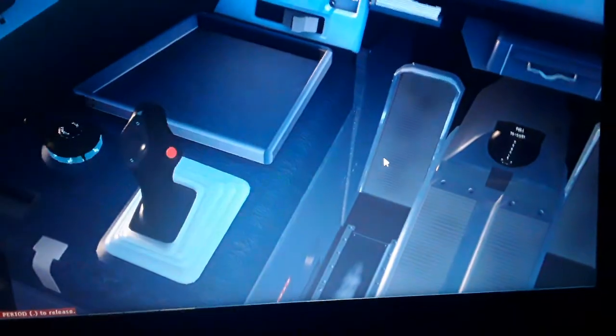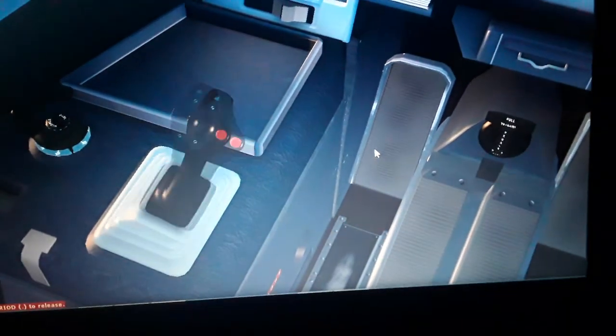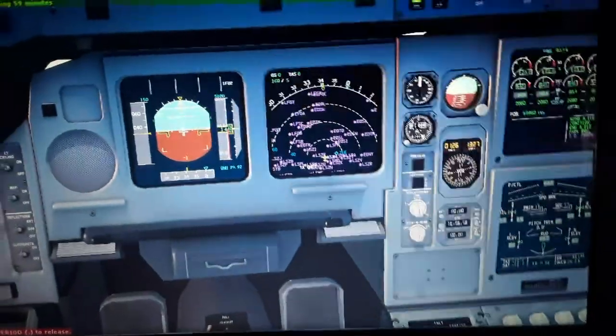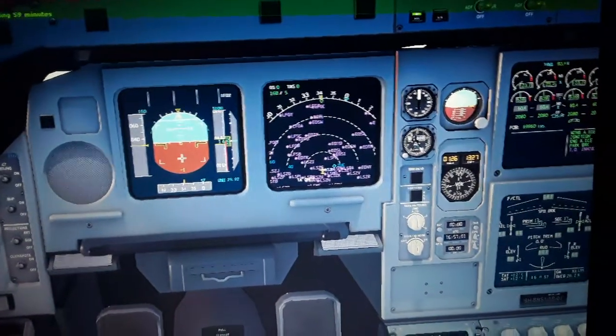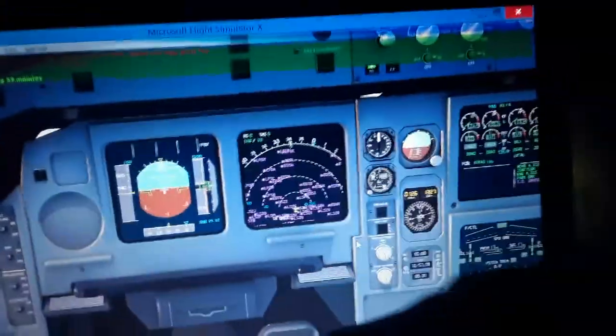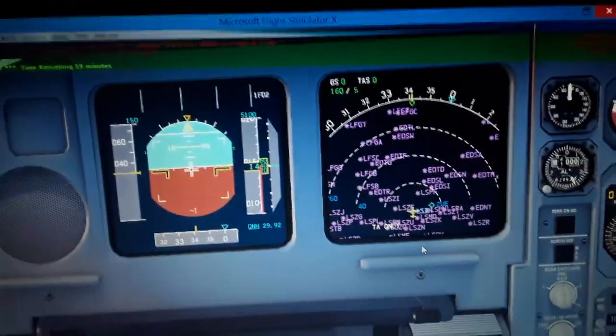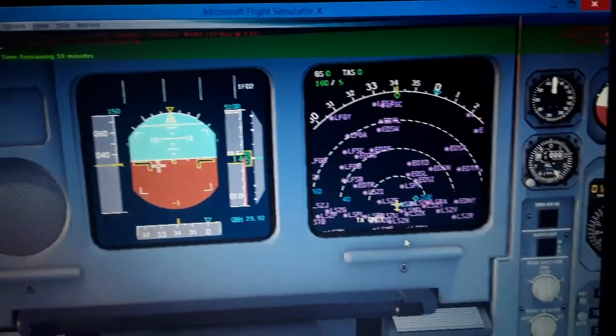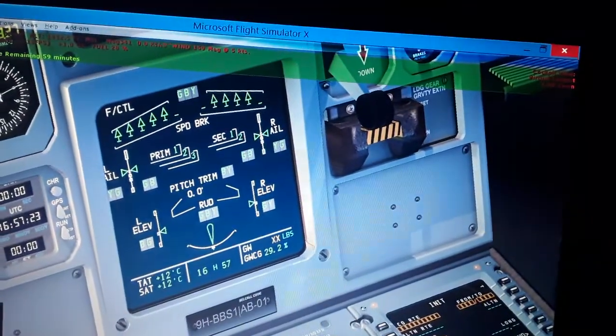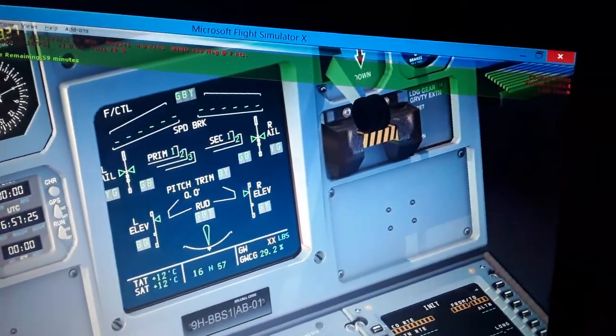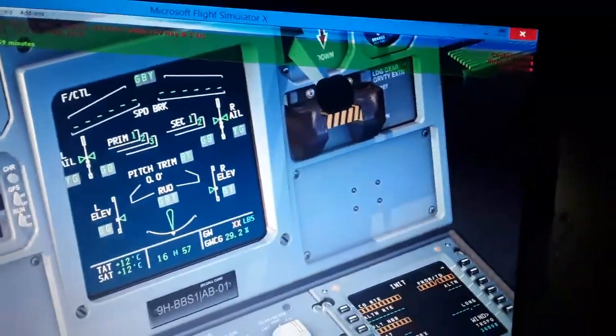So I hope you can see the input is identical pretty much to the bank angle, and also it's displayed here in the primary flight display with the stick position when we move the stick like that. I can see where my stick is. It's having a flight guidance request. So also we can see the flight control surfaces here as they move: bank roll, aileron, spoilers, elevator up and down here, and the rudder also pedals.